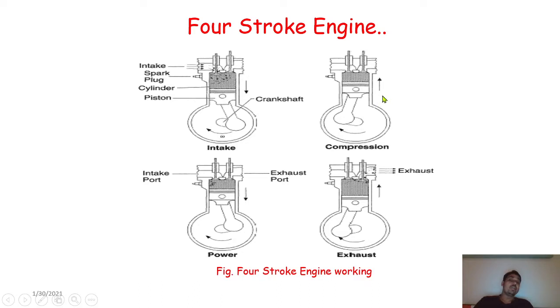Such a self inertia is also present inside this engine cylinder, and because of it the piston always moves from BDC to TDC during the compression process, and whatever amount of air-fuel mixture is present will get compressed. This is called the process of compression, and during this process both valves remain closed. For the working and closing of the valves, a valve mechanism is present. Later on we will talk about this also.